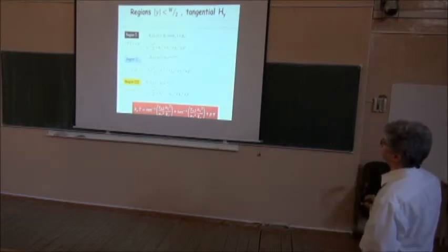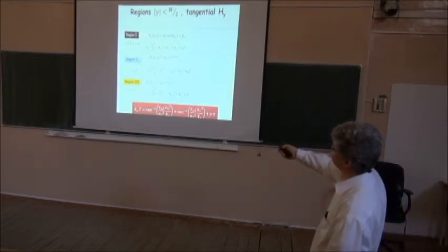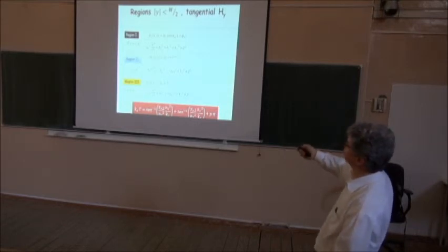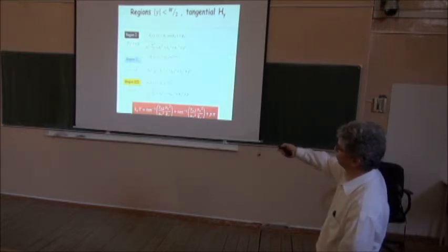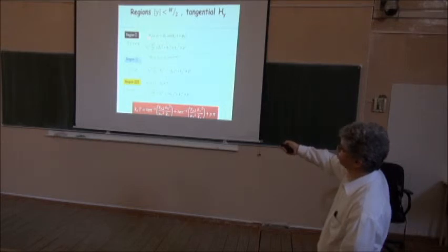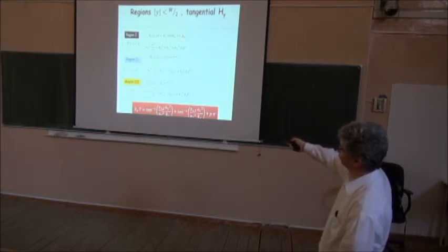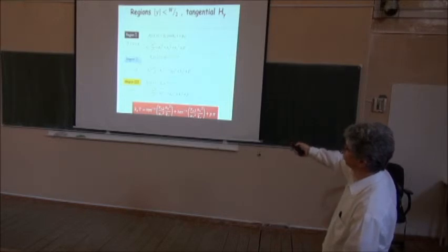So I can describe it, as we've done on the slab waveguide. That's the region where we know that I have a high refractive index, and I have an oscillatory behavior. So I'm writing my HY with a constant that defines the amplitude, I have my KX that we know how to calculate, and I have a second phase. This time I'm calling it phi 1.